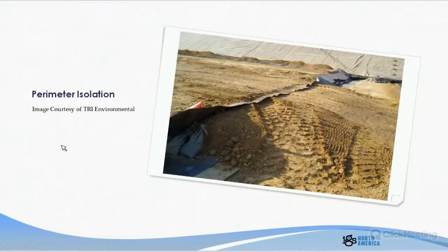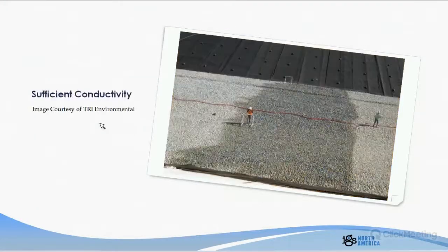Very often we have to water the cover material during the survey, and we want to drive a water truck on there, but we can't just put an access road in place because all the current is going to travel from inside to the outside via this access road. So one nice thing we could do is add an isolation flap that bisects the road completely. That allows trucks to go in and out, but it's also providing electrical isolation. Watering the cover materials is a very common thing we need to do, especially in arid climates.